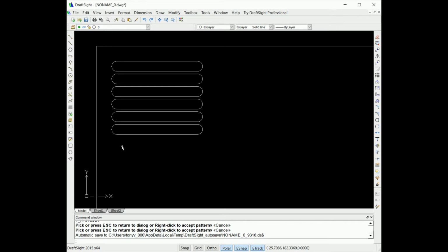And if you were putting a fan in there, of course, the fan would need mounting holes. Usually these little fans have holes in the corner. Then you would go and you would put your 4 holes. You could do that with a pattern as well if you wanted. You could do 4 holes around there to mount your fan. And then, if the wires had to pass through, then you could find the ideal place to put a hole for your wire to pass through for your fan. This is all design stuff that most of you guys should already know. It's just in the design phase you would do these kind of things.